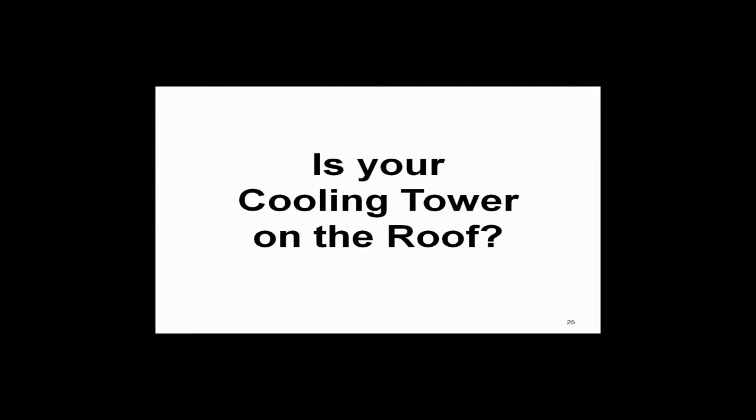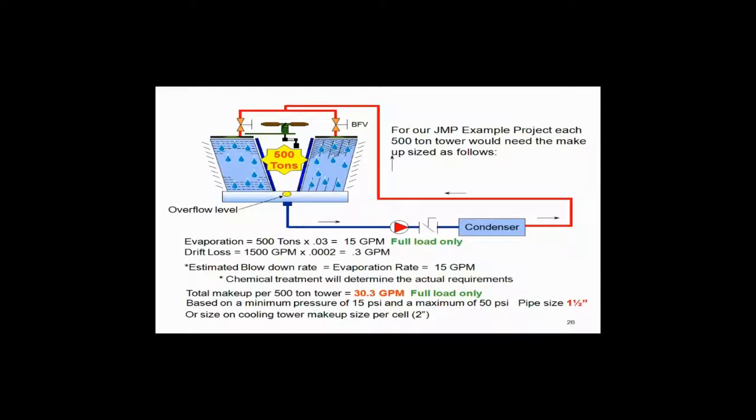Do you have a cooling tower? Is a cooling tower on the roof of your high-rise building that you're supplying a pressure booster for? Sounds like a pretty simple question, but we find a lot of times that the cooling towers are in the mechanical engineering section of the design. And I don't want to pick at anybody, but sometimes those people don't communicate to the plumbing engineer, and sometimes the plumbing engineer doesn't recognize that there's a cooling tower on the roof of the building.